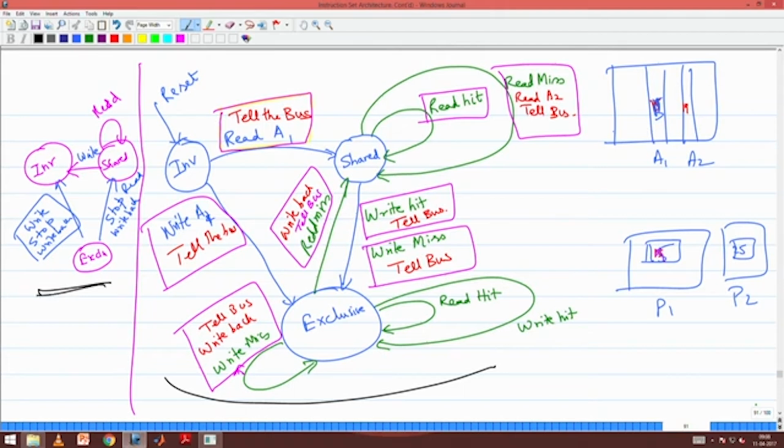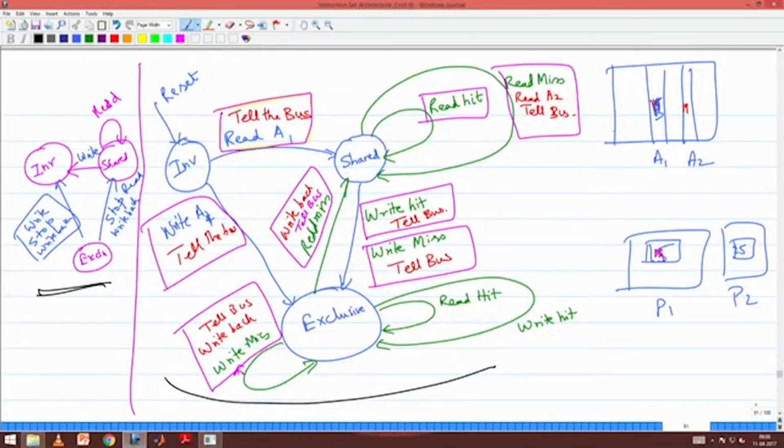Okay, the simplest of the protocols is a token ring protocol, wherein there is a common shared bus and each processor gets the token. There is one token that is rotating. When I have the token, as a processor I become the master of the bus and I can do read and write on the memory, and what happens to my own cache because of that read and write is given on the right hand side, the larger one.